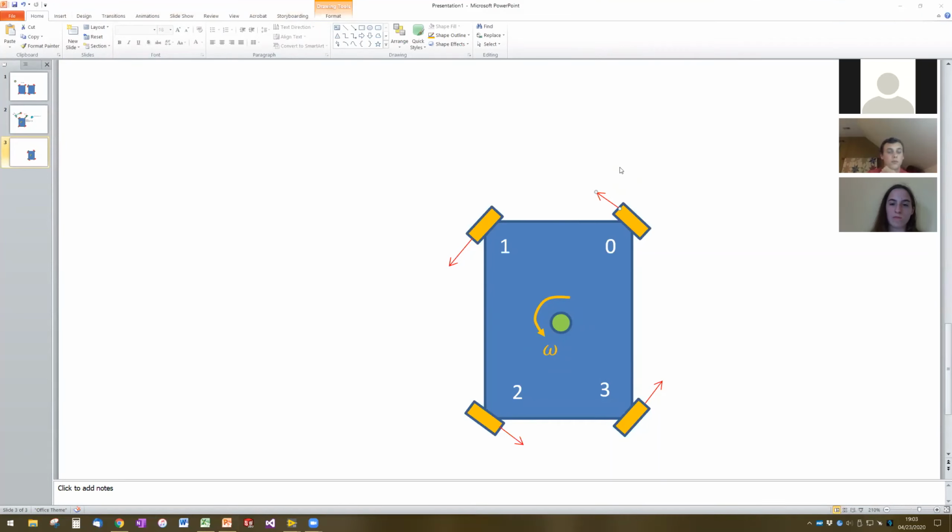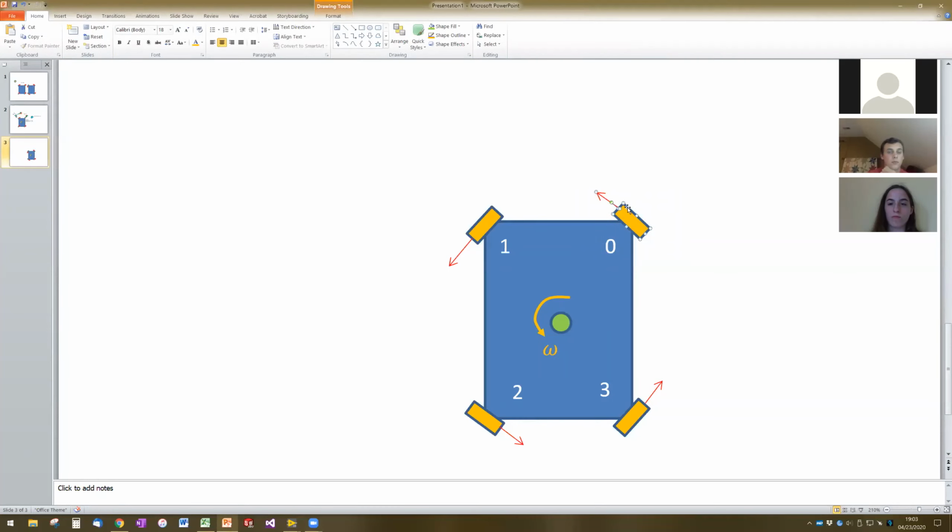What things about the wheel control how fast we're going to rotate about the center of the robot in this figure? Okay, so Alex got the easy one, the speed of the wheel. What's another thing? The orientation, because if we're turned farther out, wouldn't we spin more slowly? Okay, yeah. If the wheels were not as close to perfect as they should be, if they're like this, closer to that, you're going to spin more slowly because more is going to go into the translation. Is that what you're saying? Yeah. Okay. There's one more.